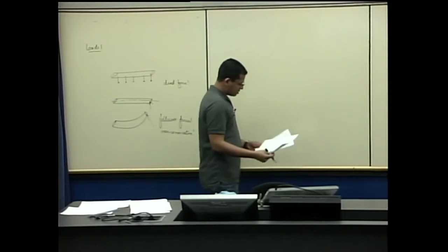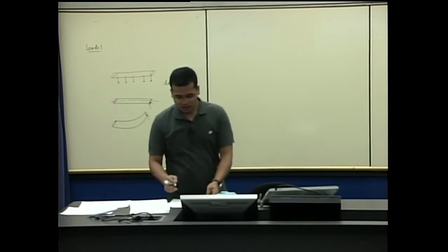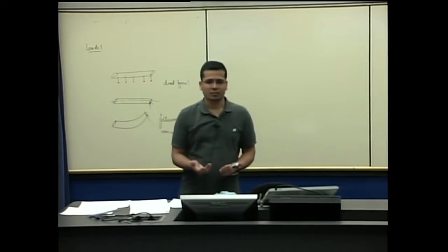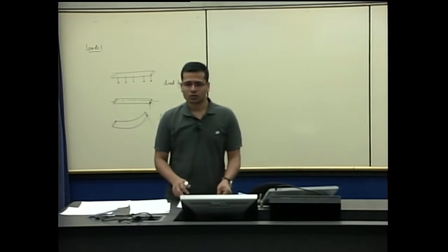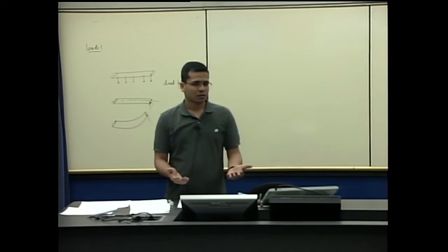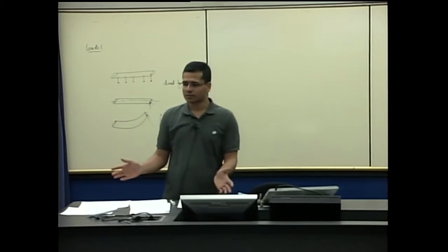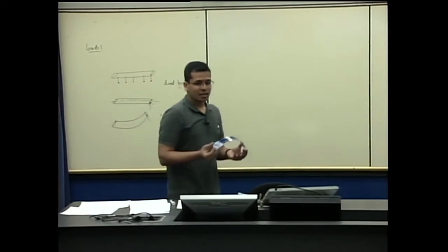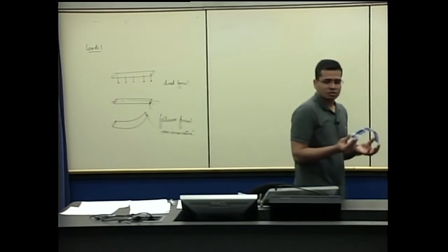Okay, so now we also discussed that there are multiple ways in which buckling can happen. One is that you do not have any equilibrium path. When it buckles, the system just collapses. There is another in which the post-buckling path is stable, so that when you keep changing the load, you keep getting a new equilibrium position. There is another type of buckling that is generally seen in structures like these. For example, just push the top surface.